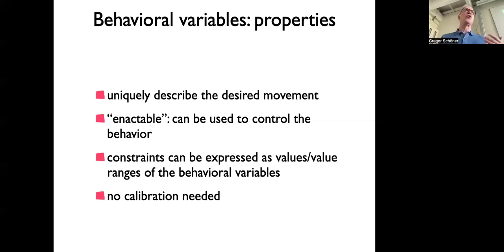And that will be controlled by that other variable, speed, which I'm not going to go into details about. If I want to track some imposed time course for the heading direction, I might have to turn a little bit, and turning means that there's a change of heading, delta phi, and that change of heading would be brought about by sending a slightly different speed to the two motors. I know how large the wheels are and how wide they are on the body.